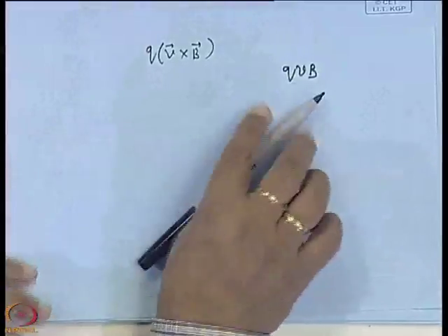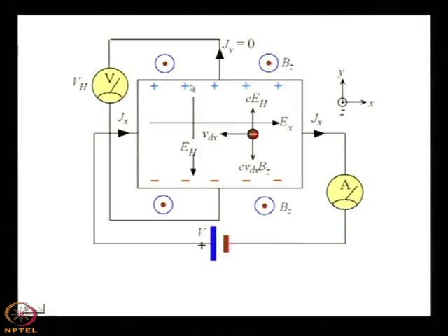Now, you see that suppose you have this type of semiconducting bar, or let us consider that this is a metal bar, forget about the semiconductor in the first case. The current passes through the positive x direction, and the magnetic field is in which direction? Z direction. So, the Hall field will be developed in the y direction.